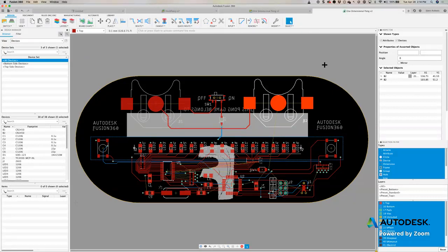Notice that now my circuit board has a version 2, while my schematic remains at version 1. Just want to make sure that you understand. It doesn't mean that they're out of synchronicity. Their forward back annotation is live. It's just I made a modification to the board that had absolutely no reflection on the schematic. Therefore, it keeps that same version while the board layout now has version 2.